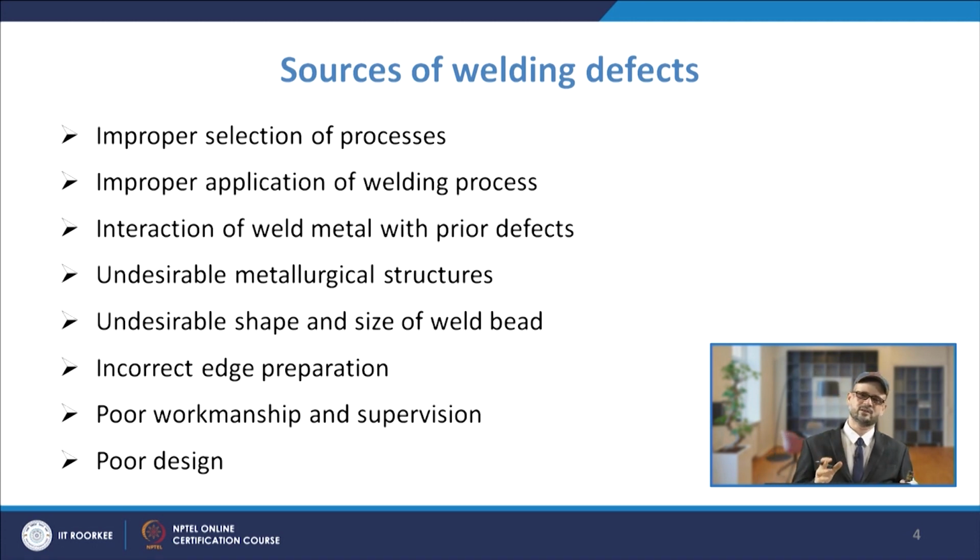So basically if you do not have properly trained manpower, then that may result in poor quality of the welding, because workmanship affects many output parameters, and that may result in stray arcing. So arcing may not be even, there may be stray arcing. Then you may have tool marks on the job.